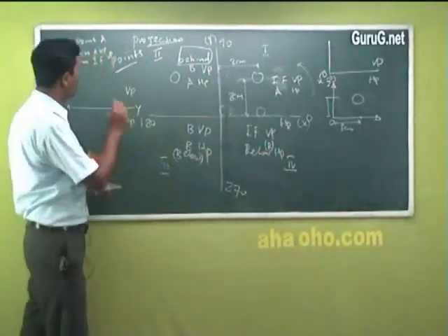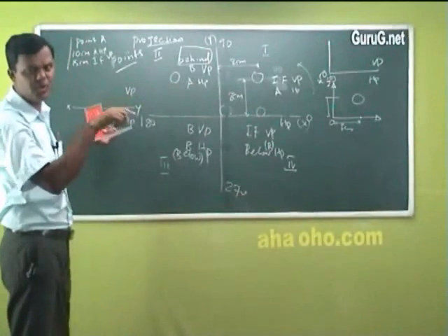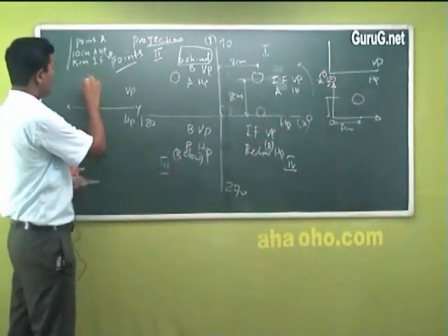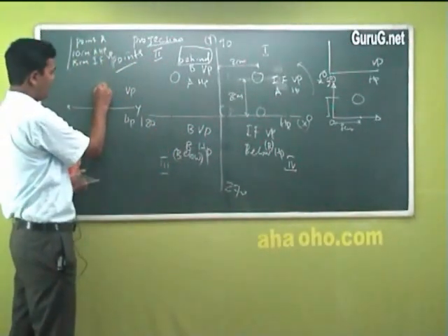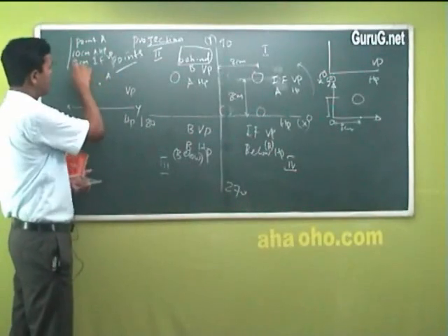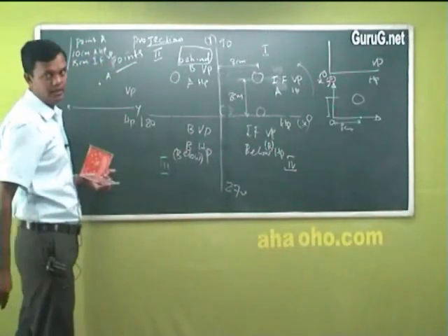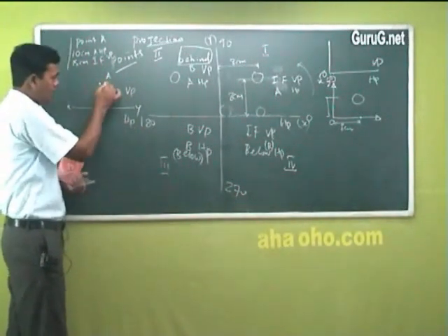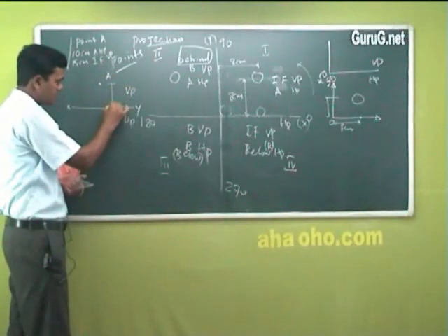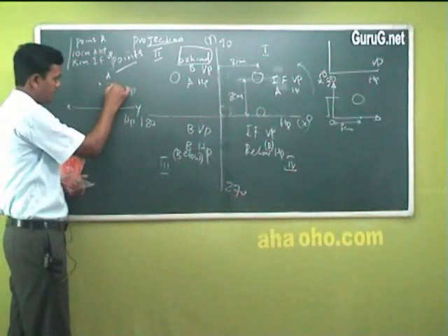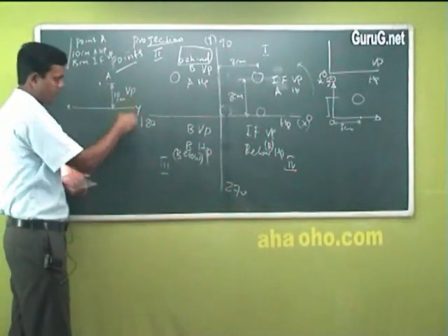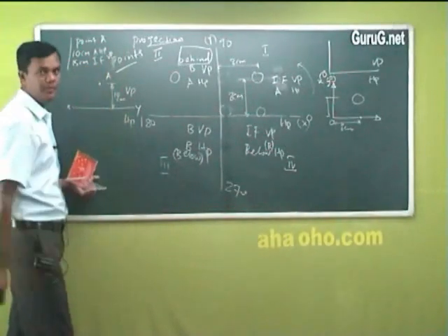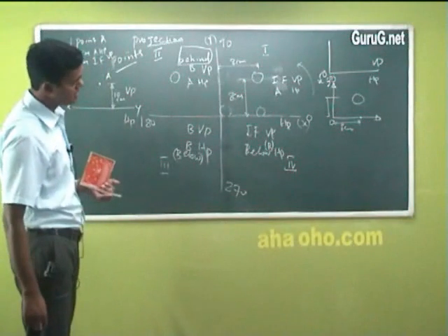Now, how will I show this in this diagram? That's the sheet, because you are drawing on an A4 sheet. Normally your notebook is an A4 sheet, right? So I'll give a point A that is 10 centimeter above HP. From this line, this is VP, HP. Above HP, this dimension shows 10 centimeter. And what is this one? 15 centimeter in front of VP. In front of VP it is 15 centimeter.